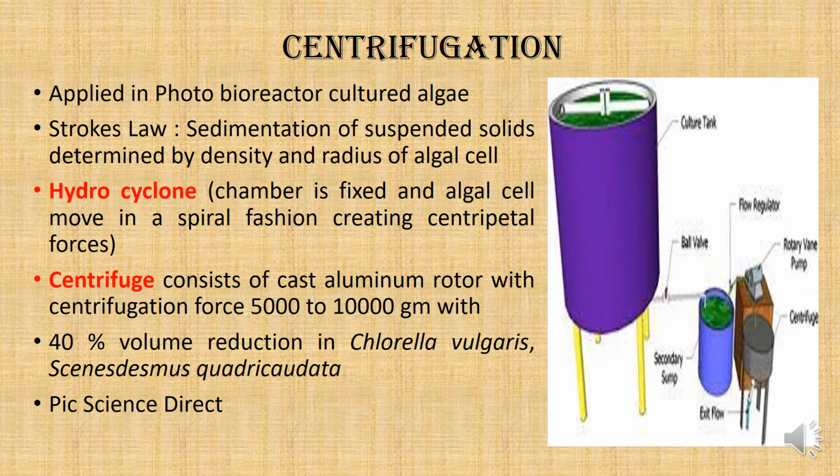The first technique in algal harvesting is centrifugation. It is a very common technique in algal harvesting and dewatering, and we know that centrifugation uses Stokes' law, that is, the rate of sedimentation depends upon the density of the algae in the culture media and also the size of the algae.